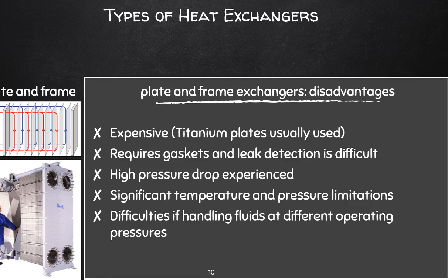Also, the pressures of the two working fluids, like I've said, should be matched closely, because you want to avoid buckling at all costs, where one fluid might collapse the confinement space of the other fluid and jeopardize the mechanical integrity of the unit, so you won't have very good heat transfer.